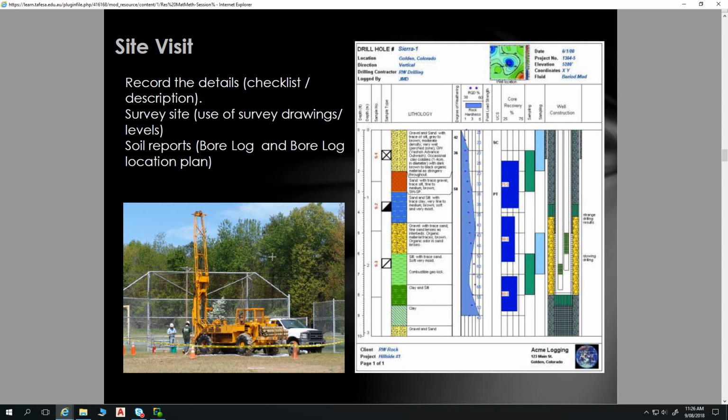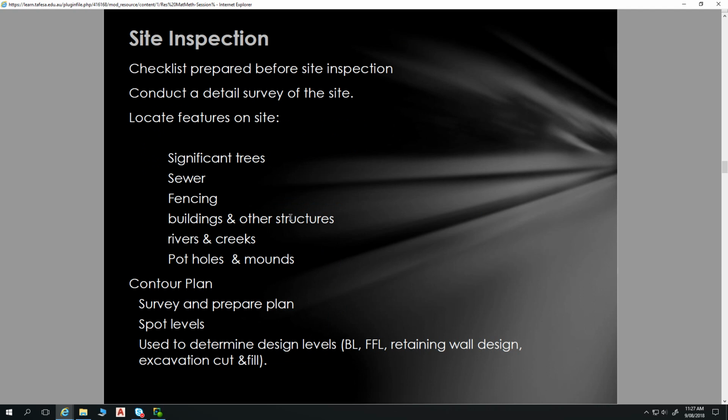It all depends on your soil and what information the engineer wants to know. But they'll take 3 or 4 samples at your site where you're looking to build a house, and maybe one where you're looking to do the on-site wastewater. And if it's a good soil sampler and engineer, they'll probably go down to 3.5, 4 meters depth. But there are companies that go, all right, we'll do 2 meters, 2 meters, 2 meters, and we'll do one of them at 3 meters. But that takes out a column of soil. Do we have a column of soil to show? No, we don't.